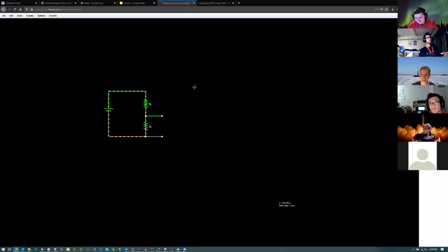And that's via Ohm's law. Yeah, exactly. So this is 10 volts, 2K. Well, not necessarily via Ohm's law, is it? It would be via Kirchhoff's rules, right? Because we have 10 volts, these are equal resistance, so we have to drop equal amounts of voltage over each resistor, right? So it would be 5 and 5.